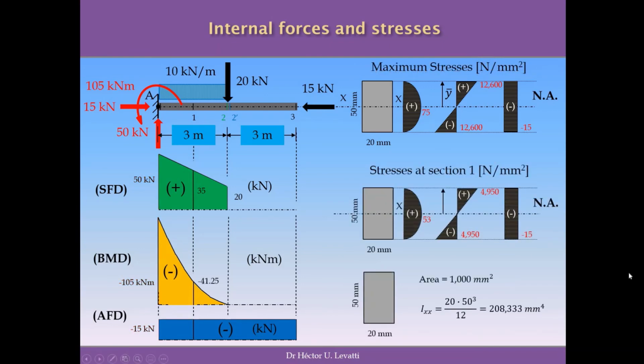An important thing to realize is that the calculations of stresses are made cross section by cross section. We have established previously, and we have all the results in here, the values of the shear stresses, bending stresses, and compressive stresses in the cross section where we have the maximum internal forces. In section A we have the maximum shear force, the maximum bending moment, and the maximum compressive internal force. So in this cross section we have established these three values for the stresses.